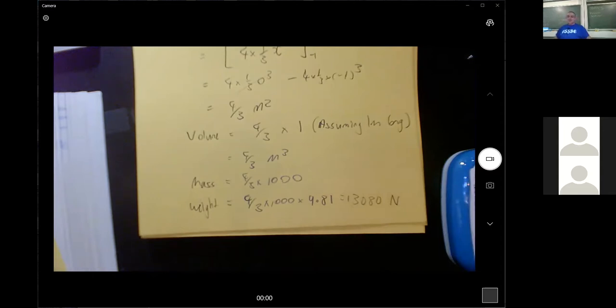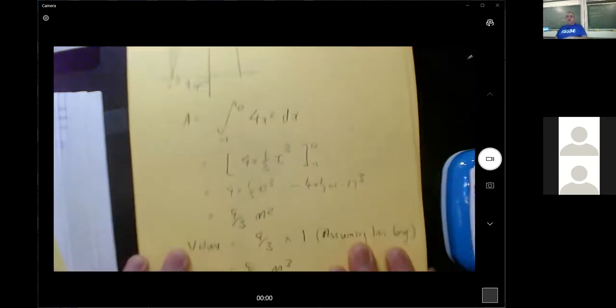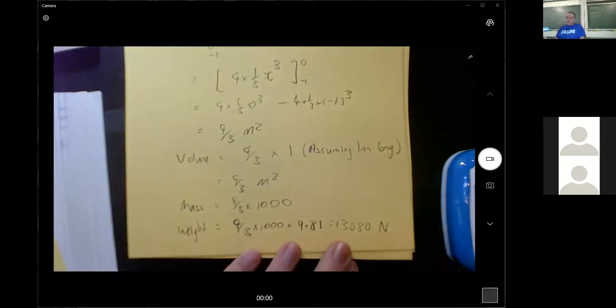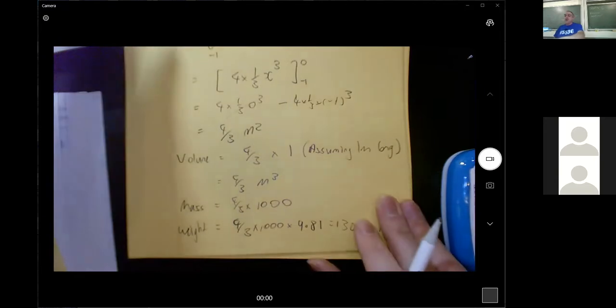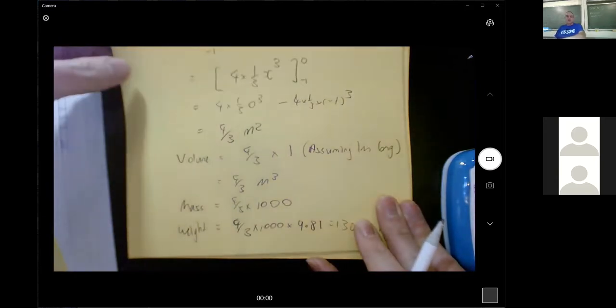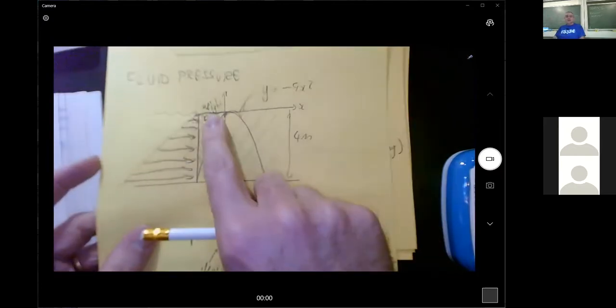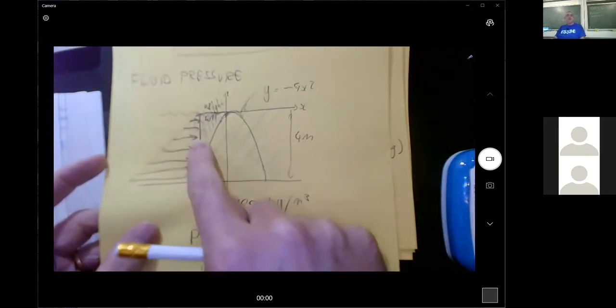Okay. So I've figured out that the weight of the water pushing down on this is, oh, sorry, no, 13,018 newtons, if I'm considering it being 1 meter deep in terms of my 1 meter wide, long in my picture. So that's one piece of this picture. I've got the weight here, and then I need to figure out what this is doing.